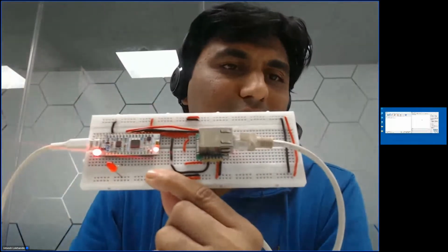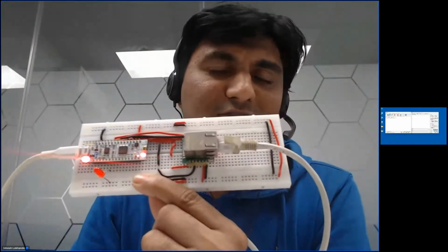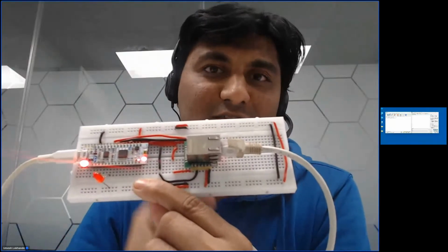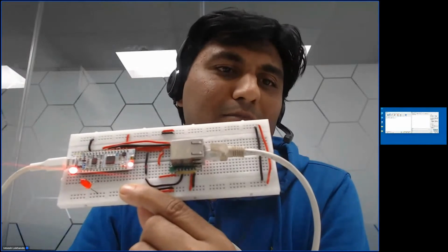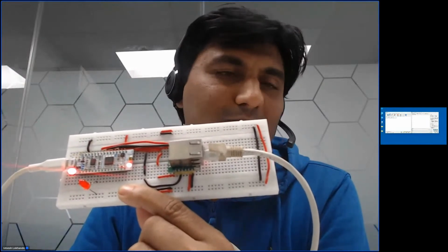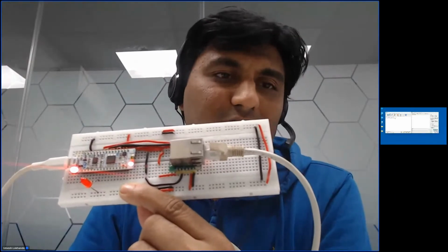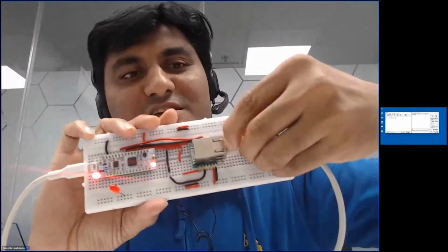So here on the serial, it says the WizNet function registers, and these WizNet functions are those 3 API callback functions in which we pass the 6 functions that we have written into the code. And then it says the link is established, initializing this device W5500, and TCP server is listening on port 5000. Again, I show you the demo for you to remember the auto negotiation feature.